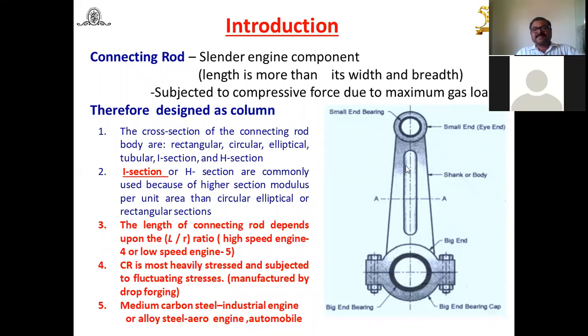Second thing, when it reciprocates and is subjected to maximum gas force or gas load, because of that it is subjected to side thrust. We have to take care of that side thrust also. And because of the reciprocating motion and the rotary motion at the big end which connects to the crank, inertia forces are also going to act on it, and we have to take care of those inertia forces also.